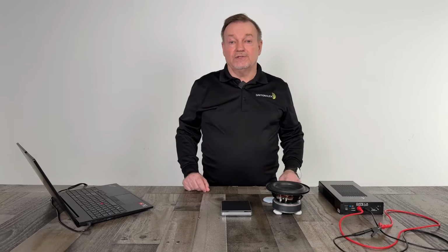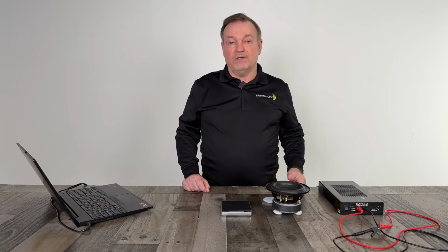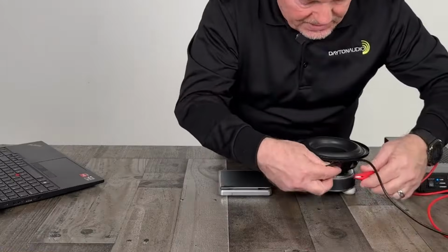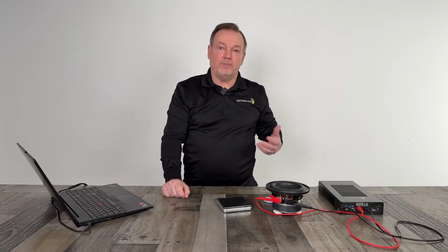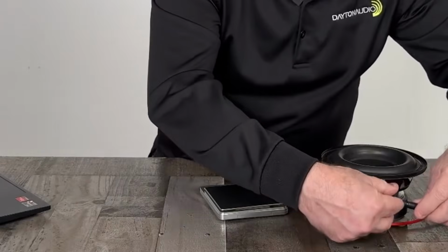Today, I'm here to talk about the DATS Loudspeaker Analyzer, or DATS LA, and how to derive small signal and large signal parameters. To do this, you will need to have the DATS LA calibrated. But since you only need to do that once, you're probably already there. We need to connect the driver. Be sure to have the polarity correct. Once we connect the driver, we're ready to do our testing.